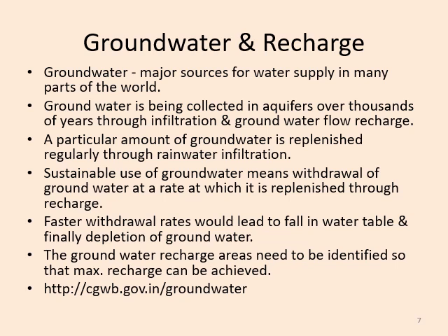The groundwater recharge areas need to be identified so that maximum recharge can be achieved. So we have to identify in which aquifer zone, or which area for a particular city or a particular state, we have to focus, so that maximum recharge can be done there.